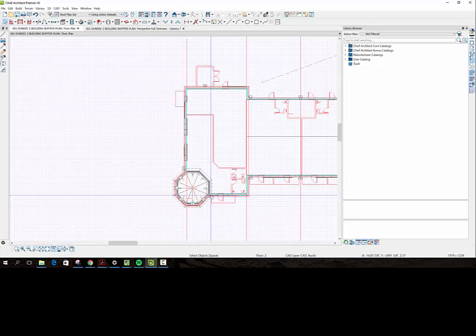What we want to do is create a high point. The trusses will be spanning from this outside wall to this wall here on the lower floor. We're going to have some wood trusses that go this way, and we can ask the truss manufacturer to create a high point. So we can drain the water there, and then use some crickets, carpenter-built crickets, to get it to our